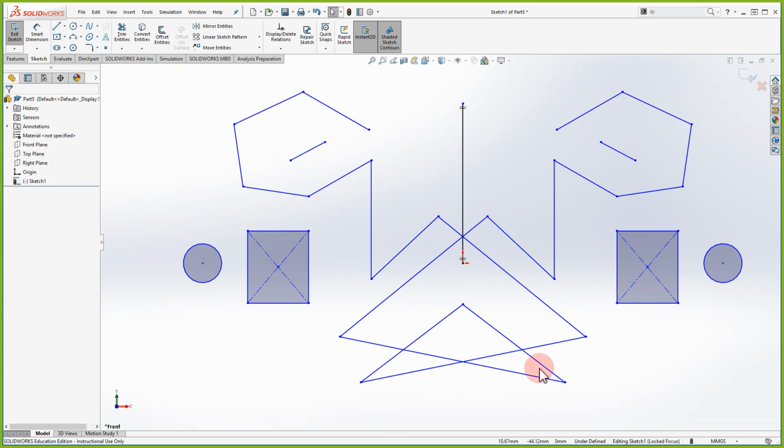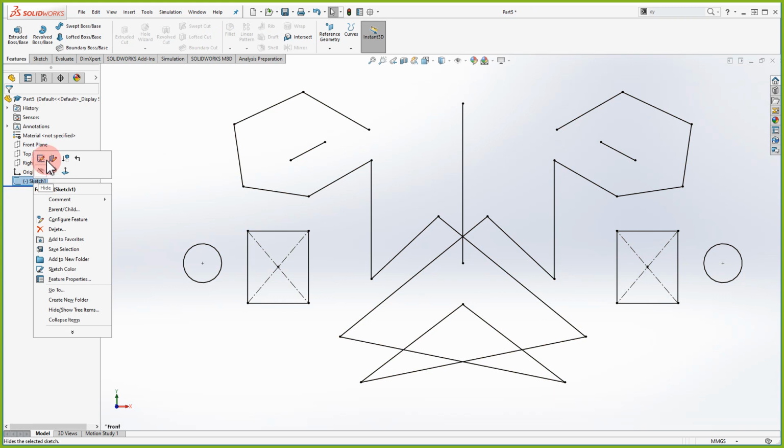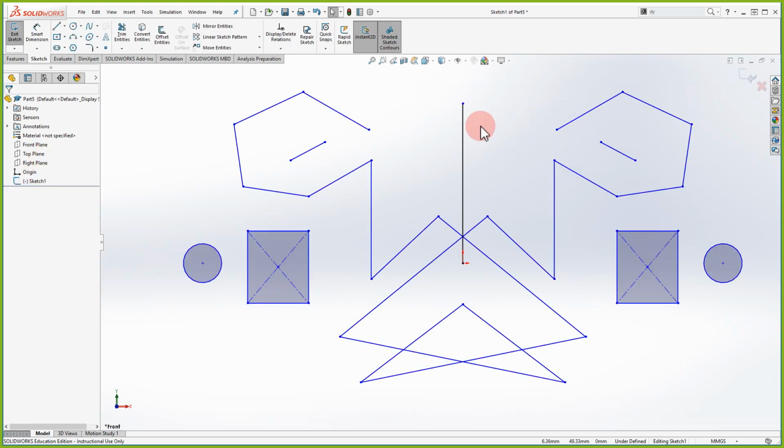So what you can do is you can just press go back, then go back to your sketch, and you notice the arrow's gone, and you're able to use it. Now, if you're tired of seeing if my sketch is closed or not, and you don't want to see the shaded each time, you do have the option to uncheck it.